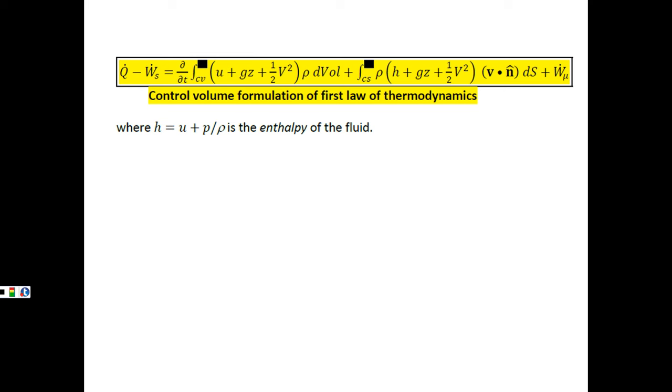Okay, so last class, we had this messy control volume formulation, which I was trying to do on the board using my cell phone, trying to describe to you from the first law of thermodynamics how the conservation of energy is considering the addition of heat into the system, minus the work done by the fluid on the system. And so we said that work term was really called a shaft work. And that may be the fluid actually pushing a propeller or something like that in the system.